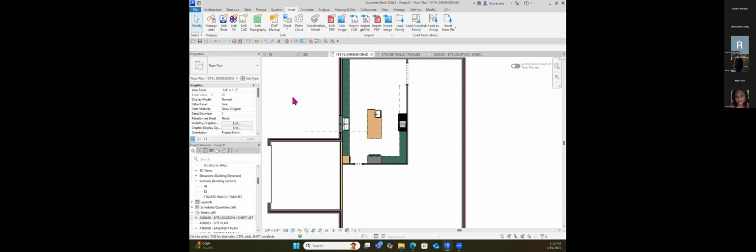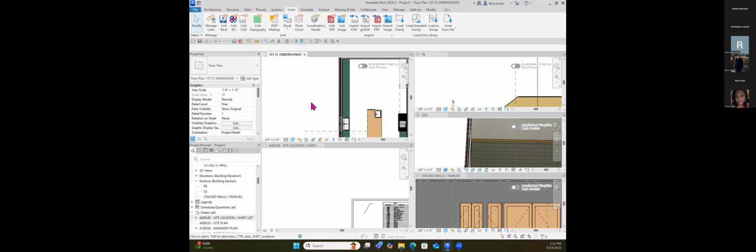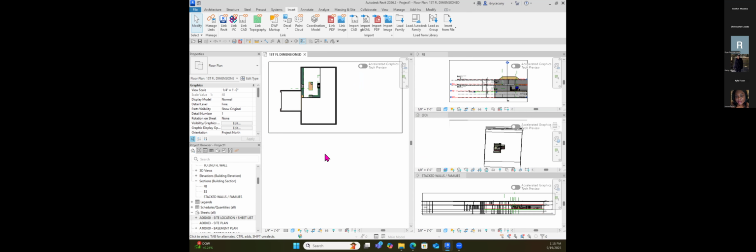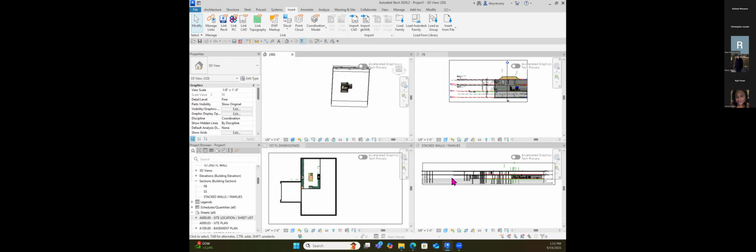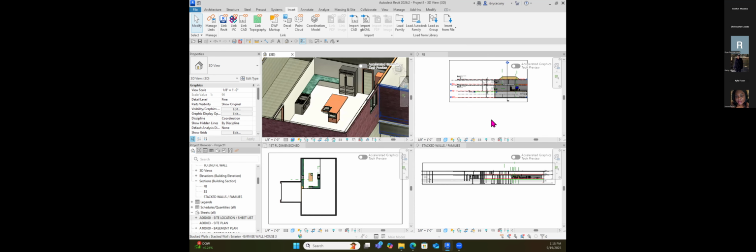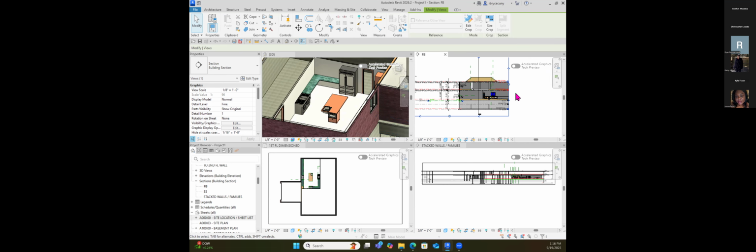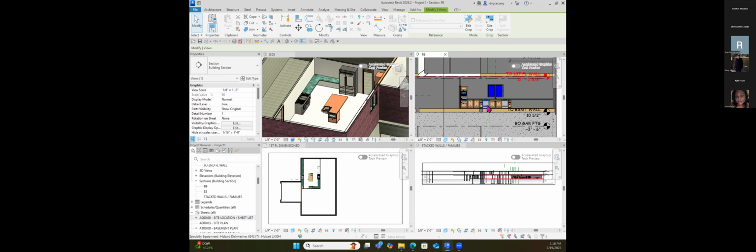I'm going to close this one and I'm going to say WT. And then I type ZA for Zoom All. Well, I don't need this one, so I can close that. And let's see if I can drag this guy over here. Yep, okay. So I have my 3D view here. If I had a bigger monitor, that would be much easier, but I don't. And this is my section view, so this is very helpful. But look, my crop region isn't showing the whole house, so I just pulled that out a little bit. All right, I like that.